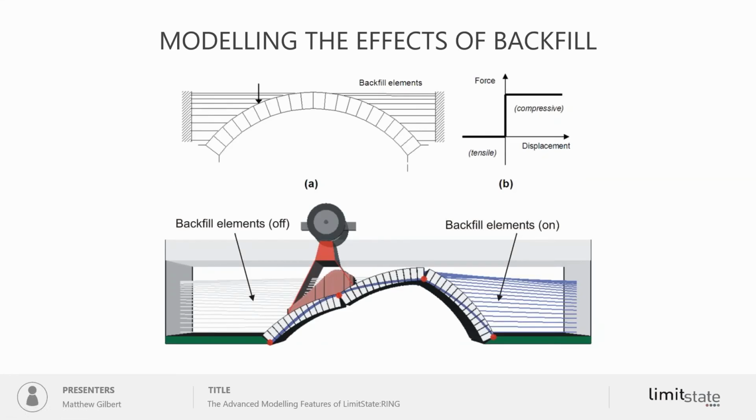Now, what I've talked about so far has been very simplified because it's been couched in terms of masonry blocks. In reality, a masonry bridge comprises not just masonry blocks but also surrounding material, typically soil backfill material. That soil backfill material does three things. It pre-stresses the masonry in the arch barrel, so it makes it more difficult to disturb effectively.